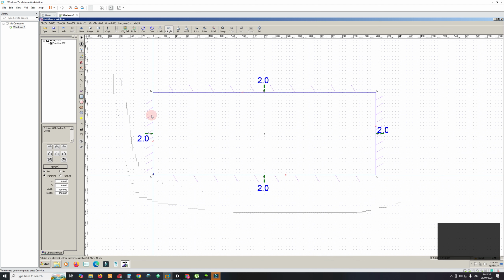While that's selected, I want to show you a couple of things. These little horizontal lines, not diagonal lines, are showing that I want to cut this piece out, but this is the piece that I want to keep, the outer edge. That's not what we want for a benchtop out of the slab. I need to rotate all that and change it to counterclockwise or clockwise.